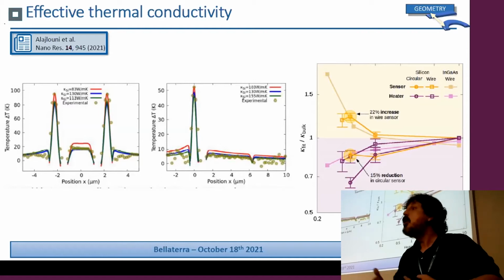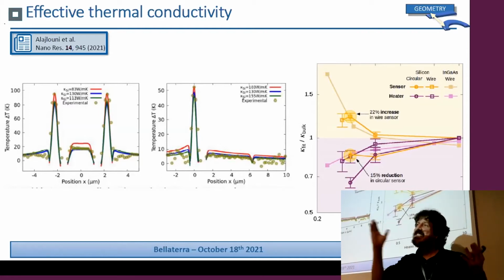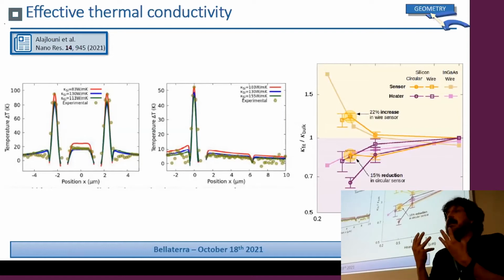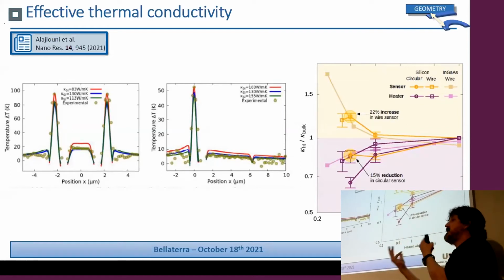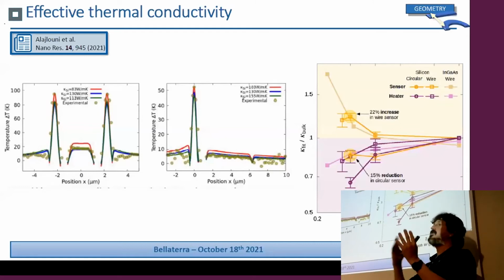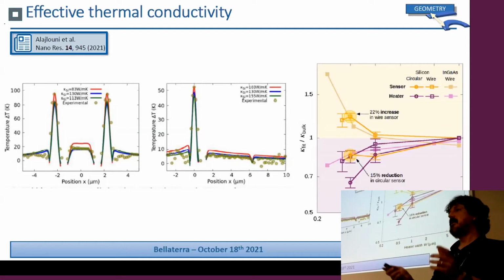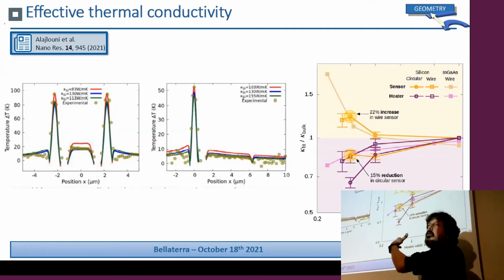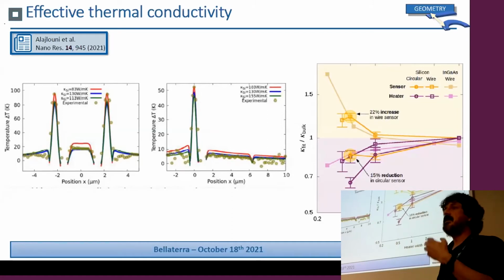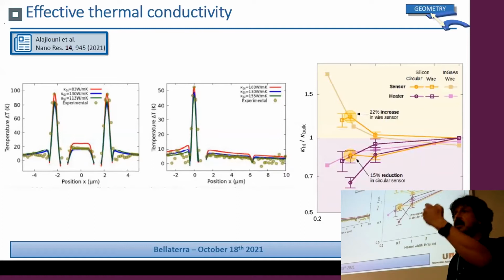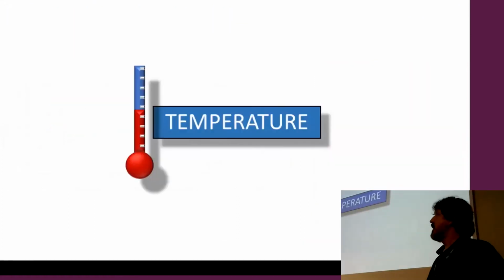So you need a lot of thermal conductivities to explain the same size. From our point of view, this completely invalidates the idea that this is a phonon versus line width thing regarding thermal boundary resistance or something like this. The powerful result that KCM gives you is that only a single L is enough to explain the results.